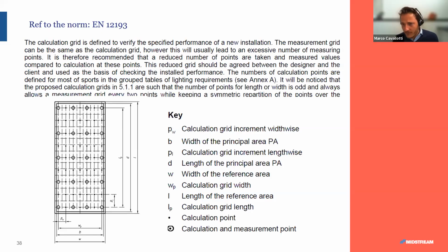Just another one from Faizul: minimum lux needed to be maintained on GSC. As shown before by Yuli, it's 50% of the apron illumination level. It says 50% because the recommendation is for 20 lux, but maybe you can have more than this, so 30 lux average on an apron. The adjacent GSC area, general area, should be 50% of 30, not 50% of the minimum requirement. So if the closer apron is 30, the GSC area should be at least 15 lux.